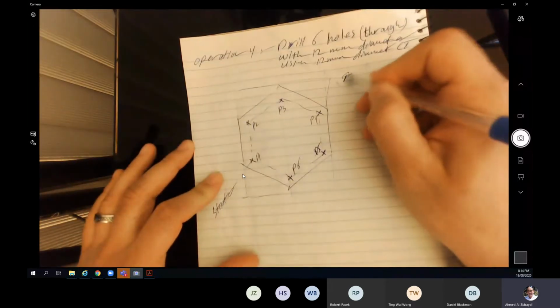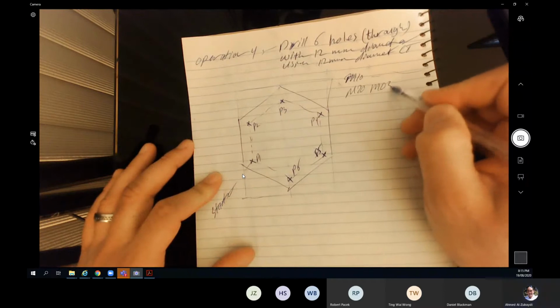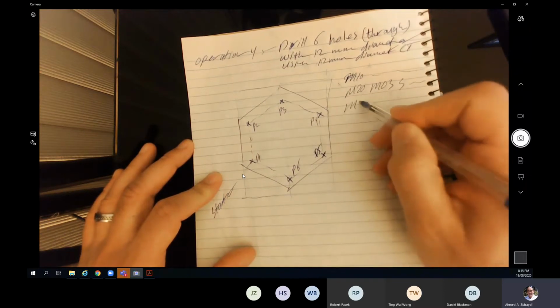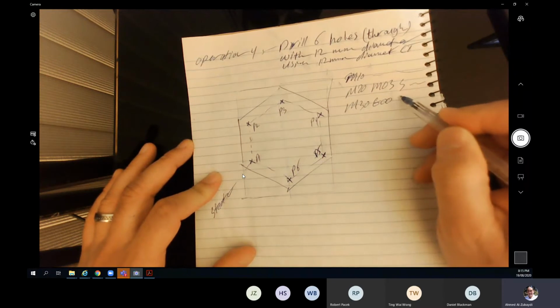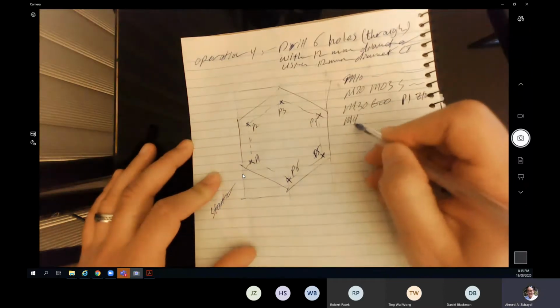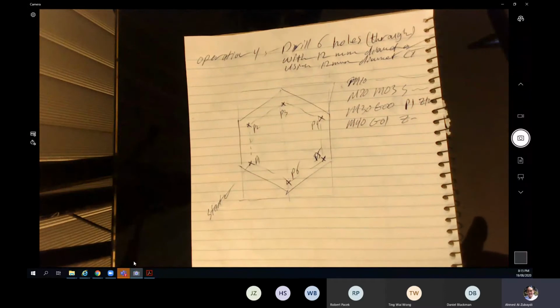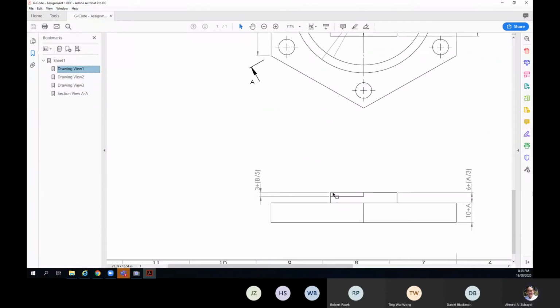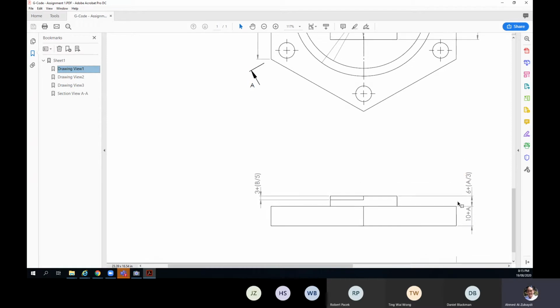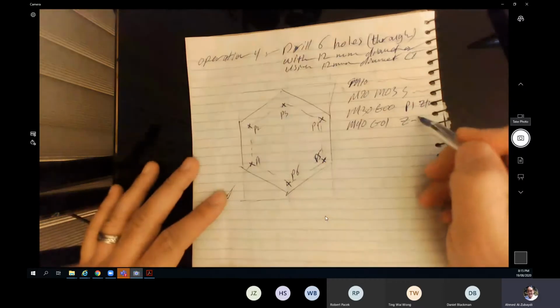Now, N10 is the definition of the tool. N20 is M03 and start the spindle. N30 is G00 to the X and Y of 0.1 with the Z of 10 millimeter. N40 is G01 to the Z of minus. Now, what was the total height? Okay, so we're going to the bottom here. So the height is going to be equal to 10 plus A plus 6 plus A over 3, which was 27. Okay, so Z is equal to minus 27.